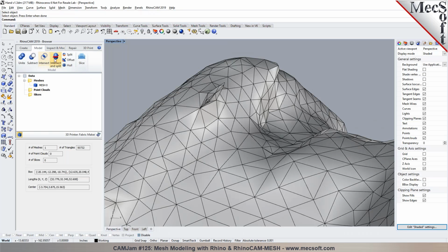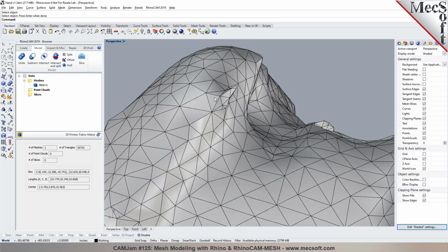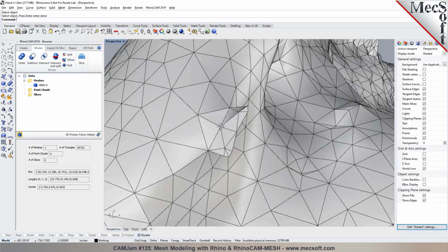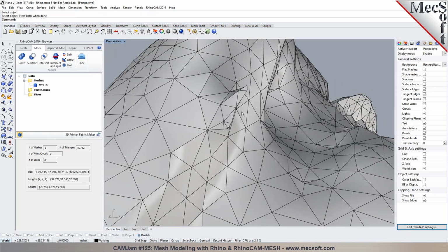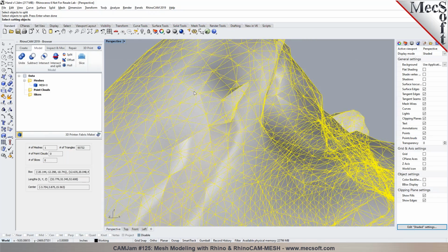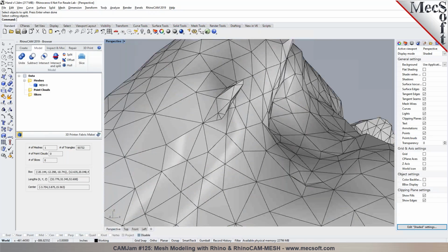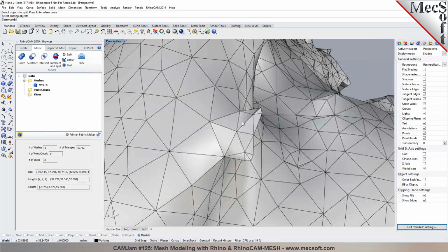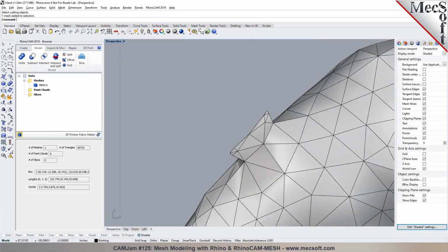Rhino also has the ability to remove those faces. You can take those faces out, but then you end up with an opening, right? Yeah, we can do a close then. We can do auto fix to automatically close it. So if you use a mesh split command, you can pick the object to split, and there's no cutting object. So basically, I will have to build something in here.